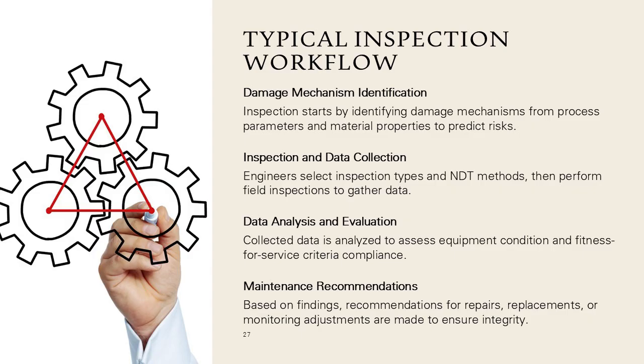This slide describes the typical workflow used in inspection and integrity management. It begins with identifying expected damage mechanisms based on process parameters, fluid chemistry, temperature, and material selection. Engineers then select the appropriate inspection type and NDT method. Field inspection activities are conducted, and the collected data is analyzed to evaluate equipment condition and determine whether it meets